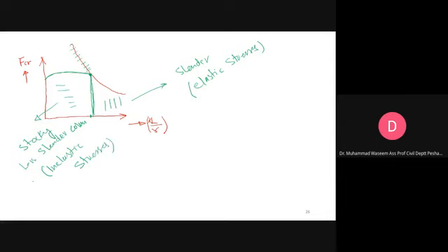Okay, in this we can estimate the critical stress using the original Euler equation, which is, I think, E pi square divided by KL over R square. And in this you can use this modified version. This is E_T pi square divided by KL over R square.